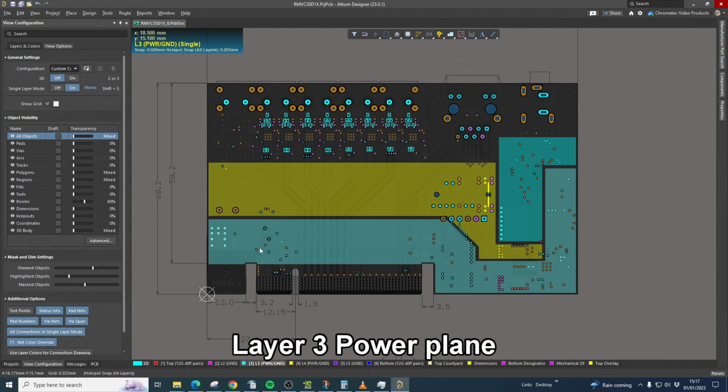Layer 3 is a power plane layer. There are 3 planes shown here. Although the power nets could have been traced, I prefer to maximize copper pour, so the planes are convenient for this purpose. I'll add ground pour to the large area at the top of the PCB later. Note the anti-pad keep-outs in this layer that are located beneath component pads that are used with high-speed signals.